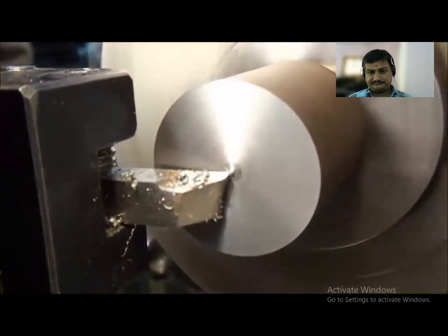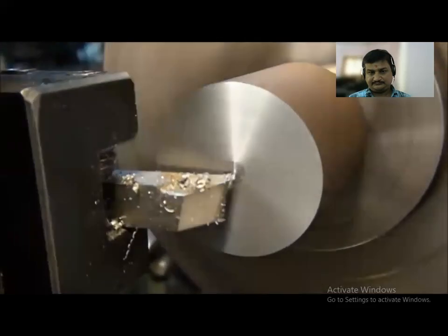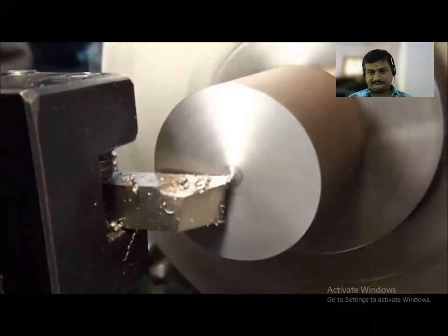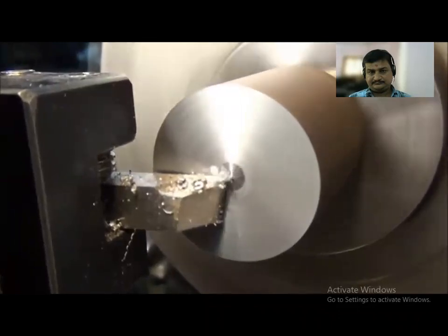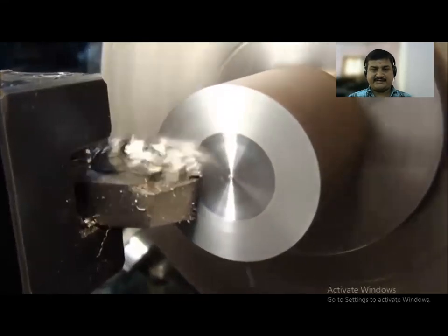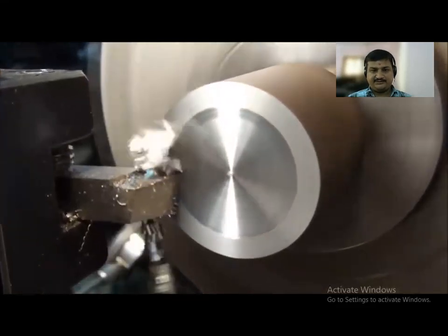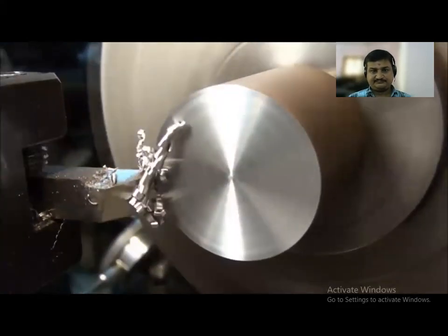Want to make sure that's gone, so if you want to drill a hole in the end of it, you don't have that little piece of aluminum or a piece of steel sticking out there to throw your drill off center. So make sure you get rid of that, and then just feed out. You can use the power feed, or you can feed it by hand, either way. And you can see the material is just cut.